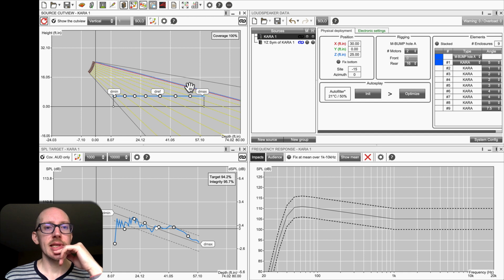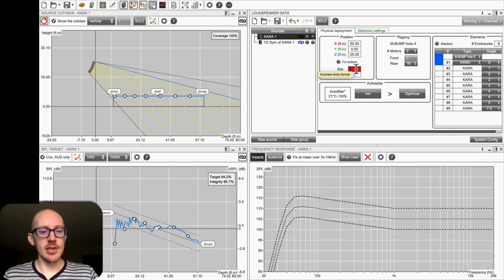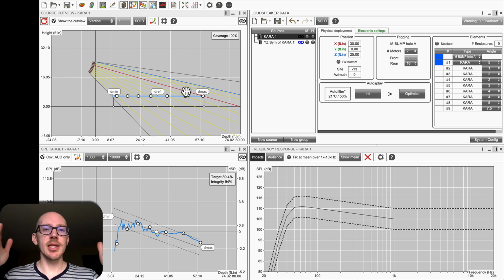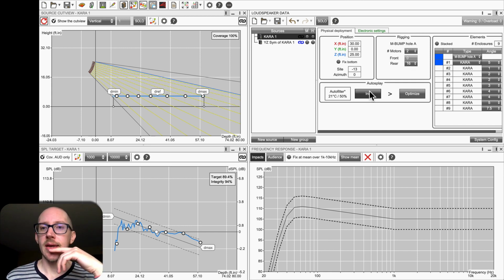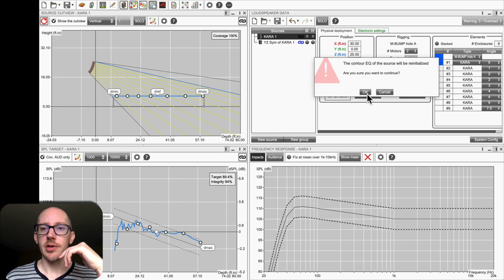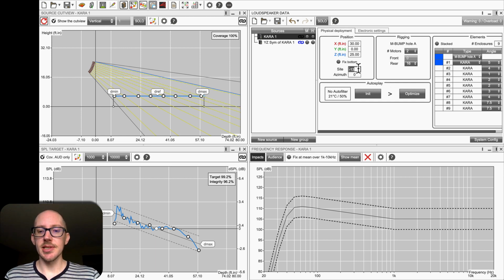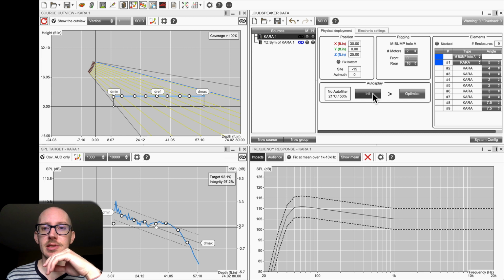And then I've noticed that Soundvision does not like an overshoot, at least not in these auto solvers. So for example, if I set this to -13, because I want these top boxes to overshoot and I want this box here to be the on axis of like that top zone, then if I do this first auto solver, it does this weird thing where it puts a big splay here, 4 degrees in between this first and second box. So you either fix that manually or you adjust this down to a point where it's not going to do that. So it's still doing that.